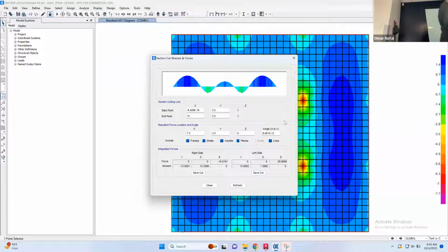All right. So what I did, I take a section around mid-span, like here. Let's see how this is gonna look like when I take this section over the column here. Can you see what happened here? The bending moments look reasonable, like at these sections. The bending moment, let's look at this color, the green, it's about 2 ton meter, 2.1 ton meter. But let's see what will happen over the column. How's the bending moment look like?